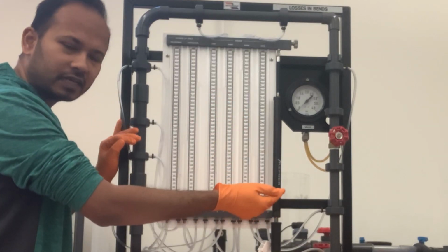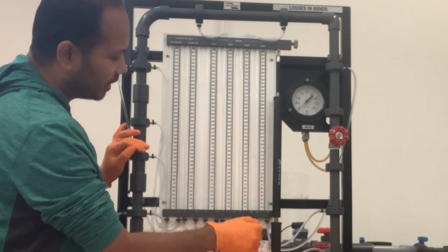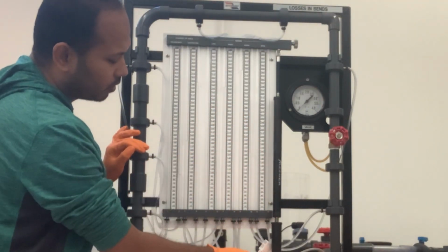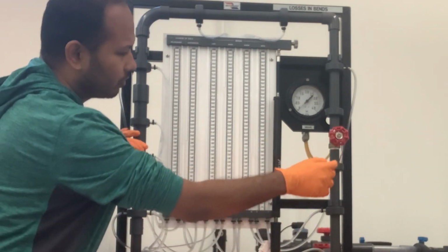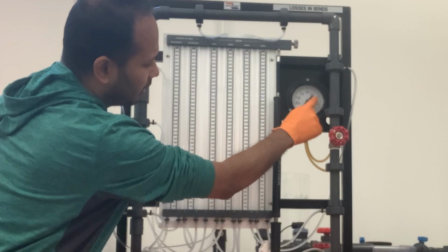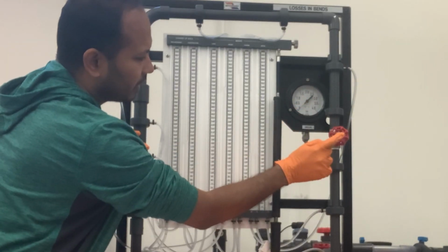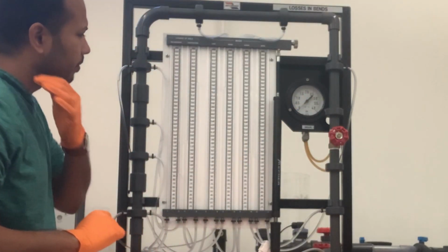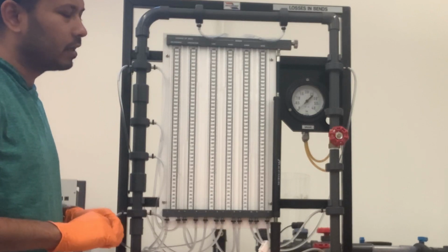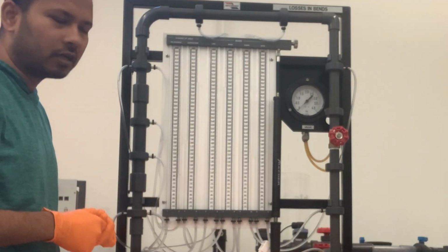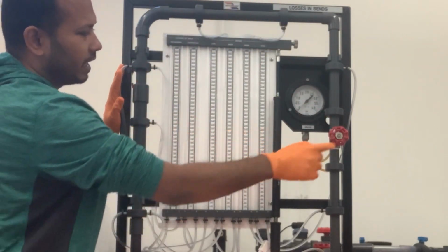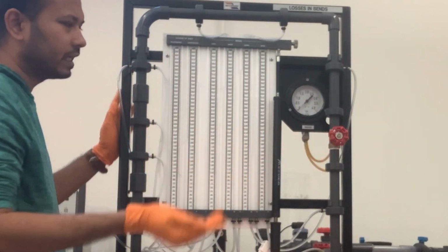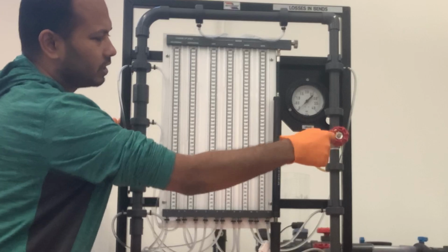On the second stage, we are not going to use this manometer. We'll close the manometer outlets and we'll use this gauge reading for the gate valve friction, the gate valve minor head loss. So the first part we're going to use all the fittings except this one, and for the second part we're going to use just this one.